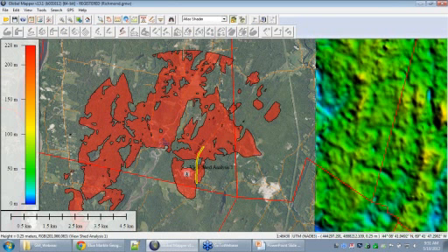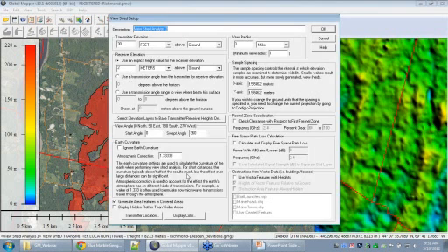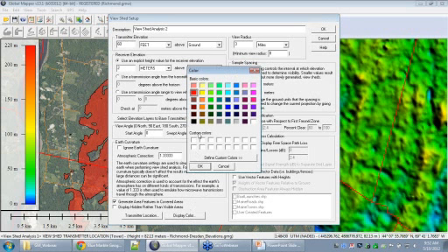One project I've been doing with this recently is a bridge project, where they're proposing a bridge that could be of various heights. So one bridge possibility would be with a road deck 80 feet over the water body, and another proposal is only 40 feet above the water body. And so in that case, we would come in here and simply do 2 view sheds. We could plop down another view shed analysis and change that transmitter height.